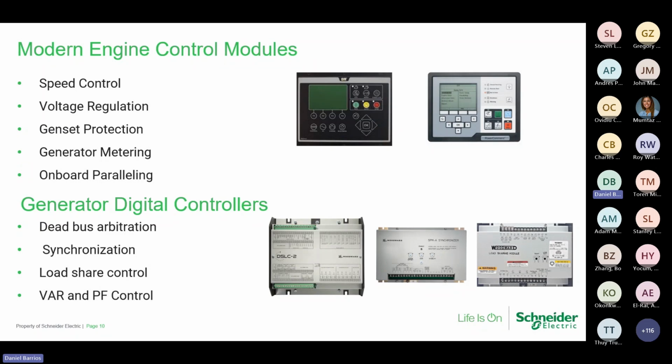Obviously, also, when you are doing paralleling, you're going to have your NFPA test that's going to have to be run on each one of your generator sets. At the end of that, the paralleling switchgear folks need to utilize that same load bank in order to set up the load sharing. If you're doing parallel with utility and we're doing a VAR or a power factor correction, we may also recommend to you to have a resistive reactive type load bank to set up those VAR controls.